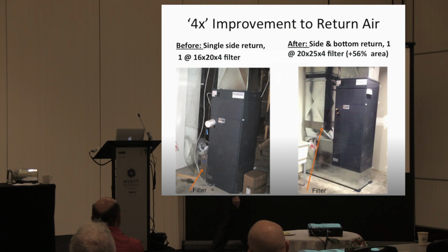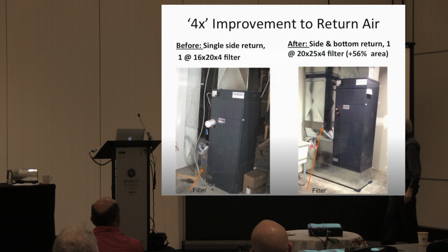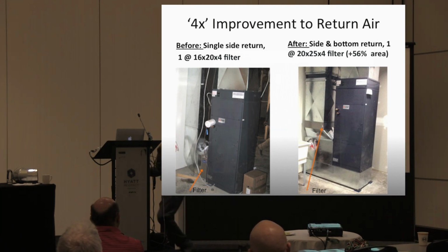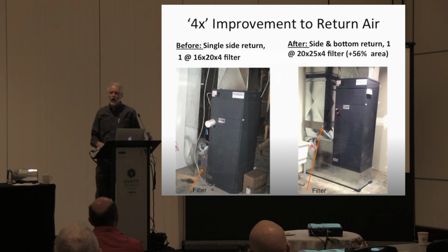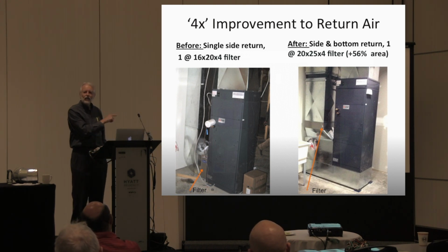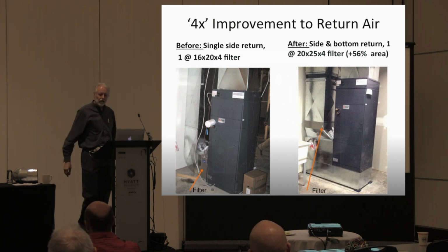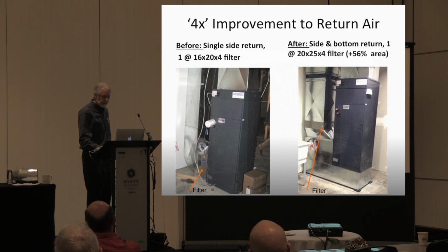When the air comes out of this fitting and it's going into that double inlet blower, some of the air is going to enter right into the blower, but a good part of it has to come all the way around inside of the other side of the blower. This fitting here is the most destructive fitting existing, and it's universal throughout this province today. And by spending a couple $300 on that one fitting, you can overcome many, many of these sins and put proper filters in at the same time.